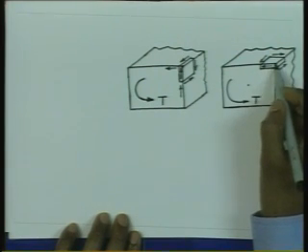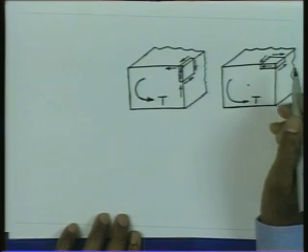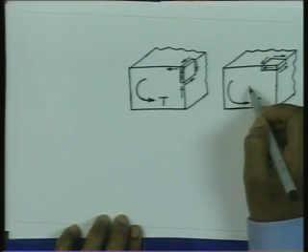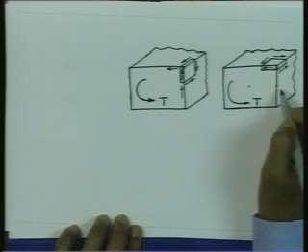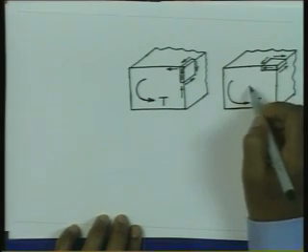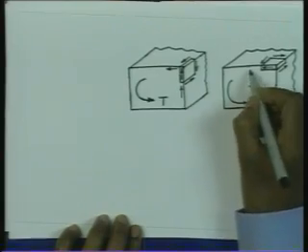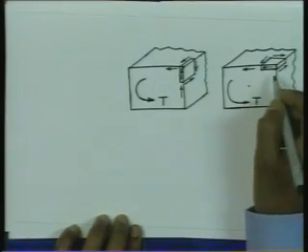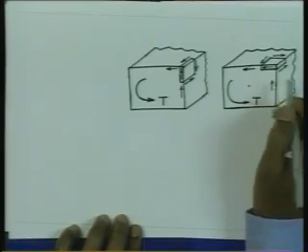The stress at the furthest point, if it is a corner, is 0, and if it is a point here somewhere, the stress is maximum, but then high stress occurs at a point which is not the furthest, it can be at a point here which is at a distance shorter than this distance. So, the stress acting parallel to this boundary, if this is a longer side than this one, then it is going to be higher than the stress acting at this point.